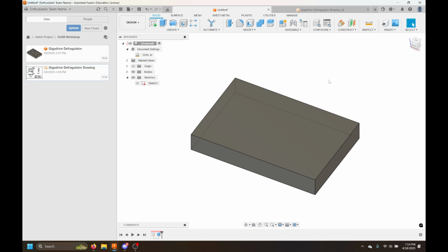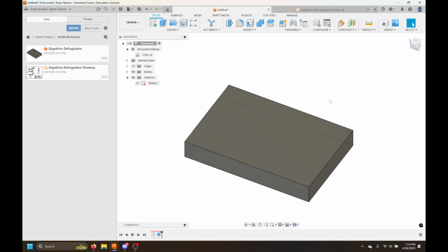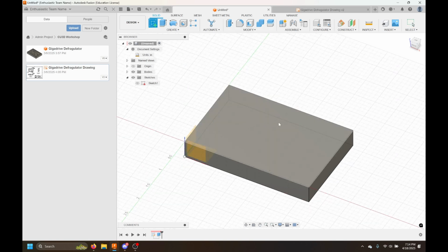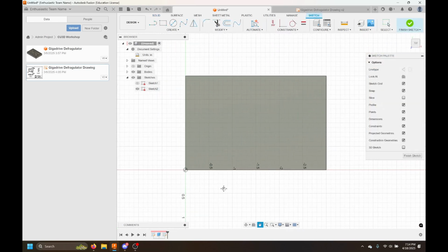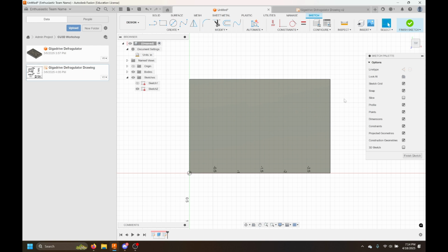All about it. Okay. So now that we've got our rectangle apart, you can see it has that indent in the rim, it has that big box, and then 3 little circles. So we're gonna do those one at a time on the top face here. To do that, we're gonna make another sketch of that outer area. So we're gonna do the sketch tool, and this time we're gonna select this whole face as our surface for the sketch. And I'm just panning it over to fit.